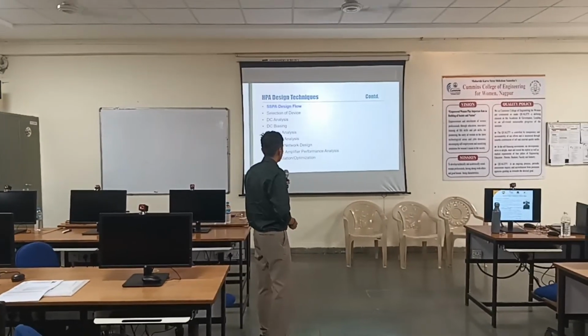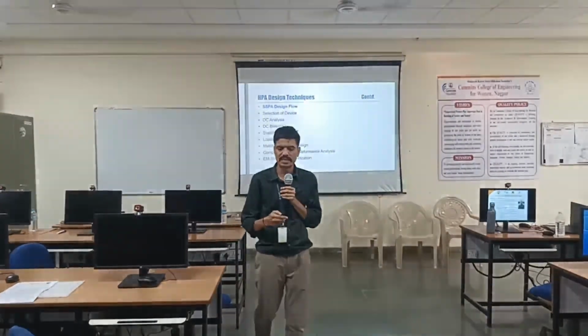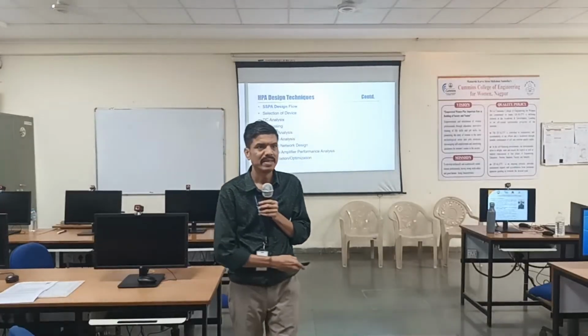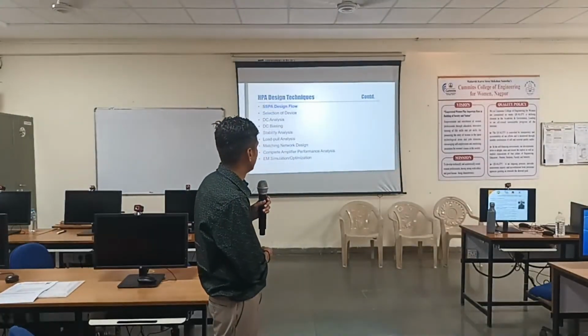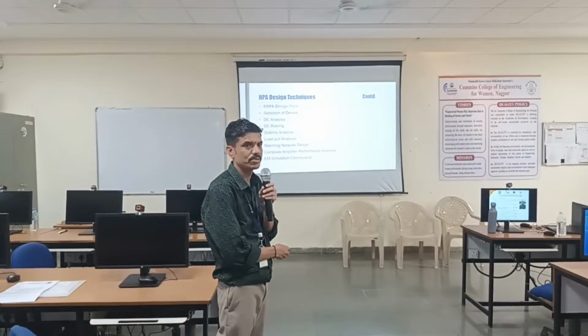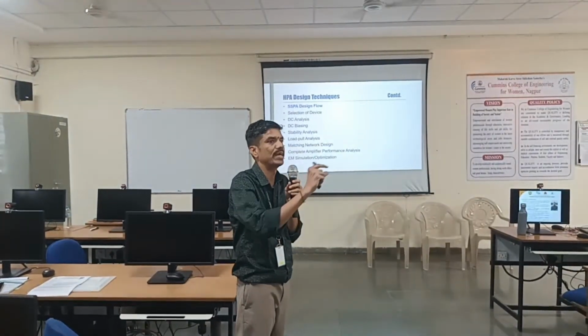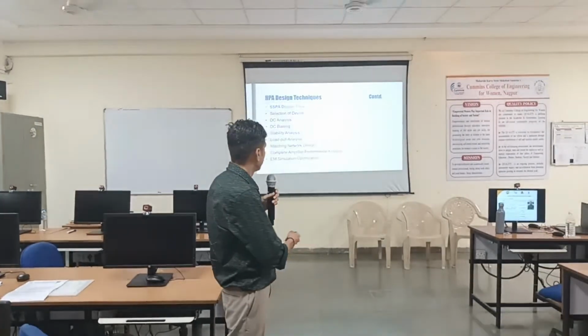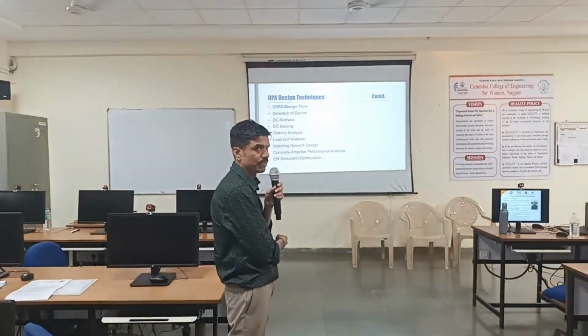So how do we design a PA? First we have to pick up the device. Then we have to carry out the DC analysis. DC analysis means I have to choose the operating point. Then we have to design a bias network.